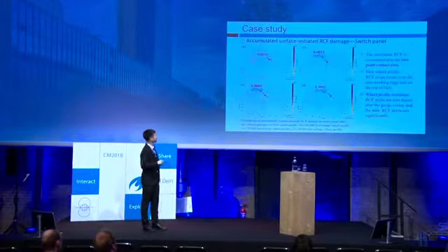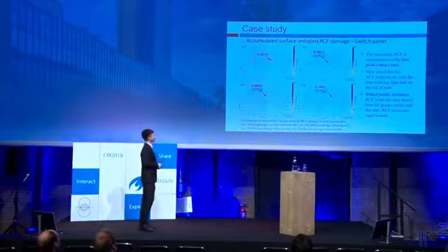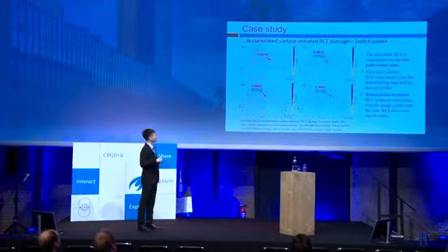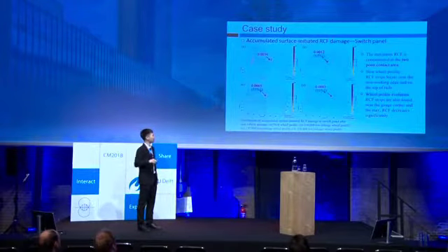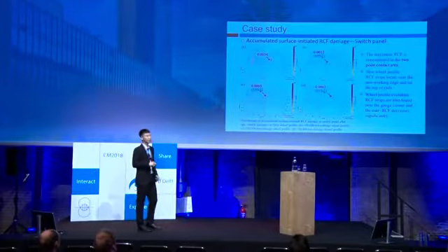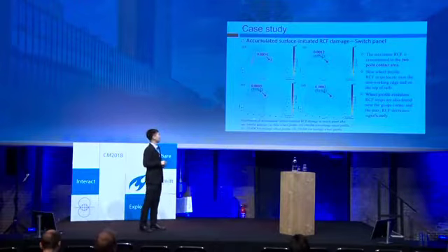Okay, we will discuss this figure now. This figure shows the distributions of the accumulated surface initial RCF damage in the switch panel after one vehicle passage. Figure A shows the simulation results of the new wheel profile. And it is found that the maximum RCF is mainly focused on the head and on the top of the rail.